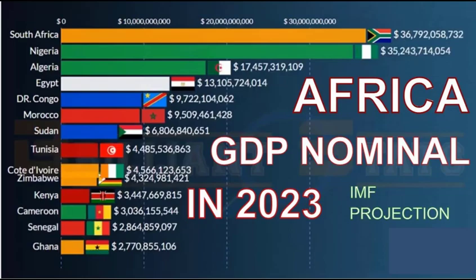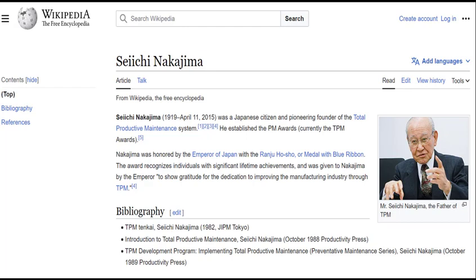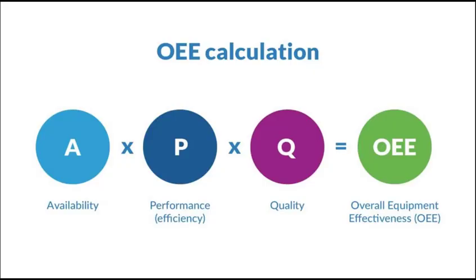In a similar vein, OEE was invented in the 1960s by the Japanese pioneer Seiichi Nakajima and was first written about in a book in 1989 called TPM, Total Productive Maintenance. OEE is expressed as a percentage from 0 to 100, where an OEE score of 100% equals the manufacturing unit operating at full capacity. It creates a single currency and a global standard algorithm to benchmark diverse production lines and diverse factories. It breaks down the production losses into three levers, namely availability, productivity, and quality yield rate.